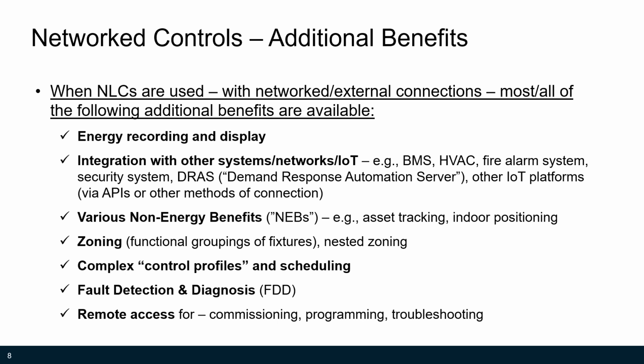It will allow you to create zones or groups of fixtures, sometimes in complex arrangements that I would call nested zoning. They may allow you to create complex control profiles, or basically definitions of how things behave, and then scheduling to allow you to tell the system how you want things to behave at different times. They very likely will contain some method of fault detection and diagnosis. And then finally, they may also allow for remote access, which can be great for commissioning, programming, or troubleshooting.